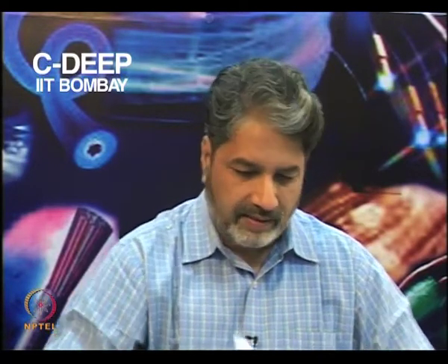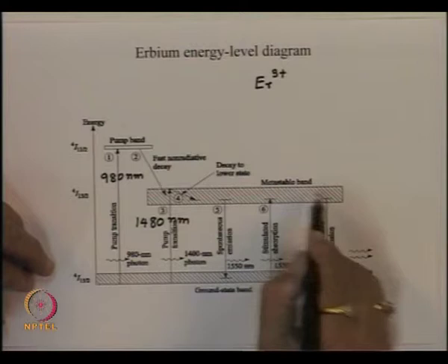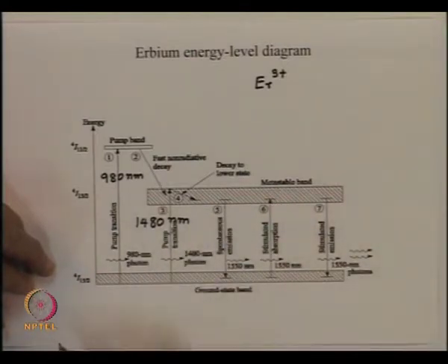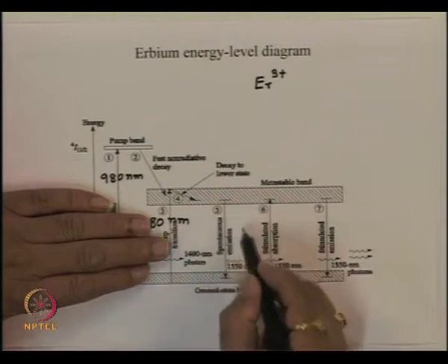We also see now that if we do not put any signal inside the amplifier, then because of the band diagram we create population inversion, and now you have the electrons accumulated in this region which will make downward transition, and since there is no signal present here, the downward transition will be because of spontaneous emission.